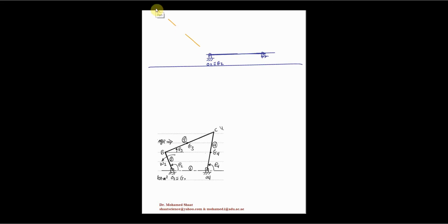Then over this line, you're just gonna measure the O2B, which is already given as 30 millimeter. It means that you're just gonna measure 3 centimeters and you're gonna mark a point. So we're gonna measure 3 centimeters and mark a point here. Then your objective is just to connect these 2 points together with a line. You're gonna set up the second link. This is gonna give us the link number 2. Make sense?